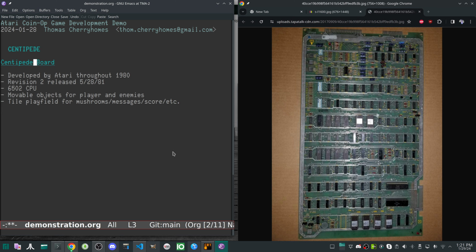And it would have the necessary CPU, in this case, a 6502, and any I/O chips, such as a PIA for talking to the outside world, and have the various connectors, as you can see, to talk to the joysticks, the monitor, all of the controls, the buttons, etc. What we're actually going to be modifying here corresponds exactly to these four EPROM chips down here at the bottom of the board and these two EPROM chips here at the center of the board.